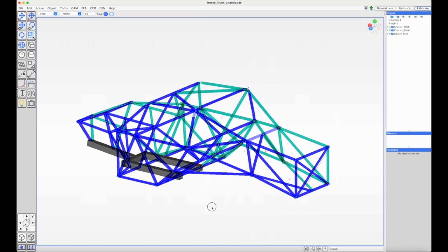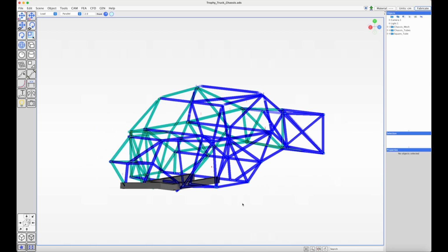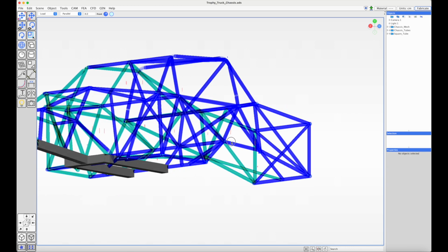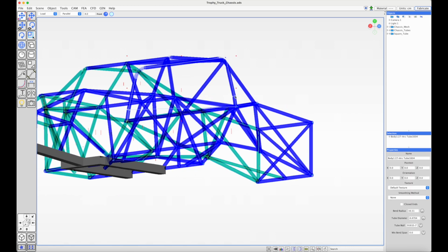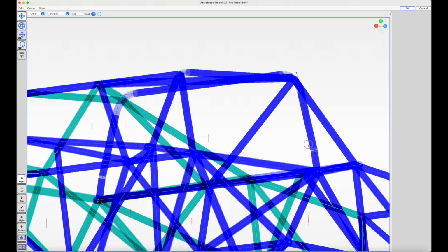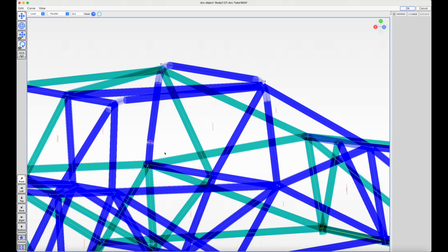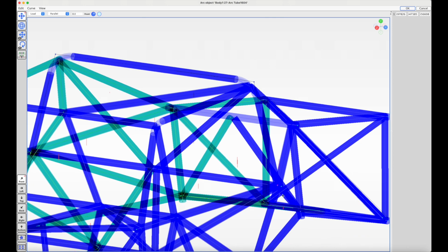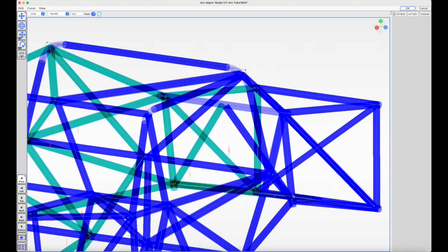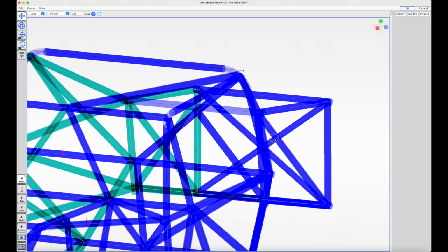One of the things that I've noticed that I'll have to address is the reason that this tube had a curve here is because of the way that it converts from the mesh. It's going to find the center position where the notch coping was, but the notch coping points don't actually represent the center of the tube if the cope is at an angle.